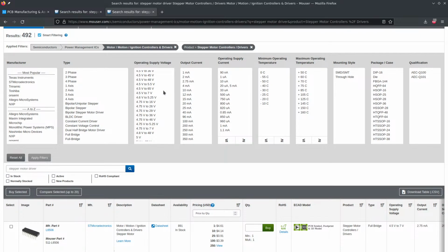What these actually do is what's called current chopping. So if it's rated for, I don't know for certain off the top of my head, I think these are about 1.5 amps. What the controller I was showing you does for you is you set a current value on it. These do like an amp before they overheat.